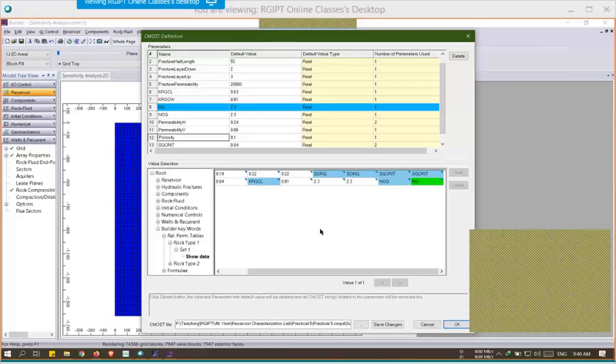When checking the relative permeability table, we are mostly changing the values for the liquid gas table, because the water oil ratio, the gas oil ratio, the cumulative gas and the cumulative oil were having much more error. So that's why we are mostly selecting the parameters that are relevant to the gas liquid table.